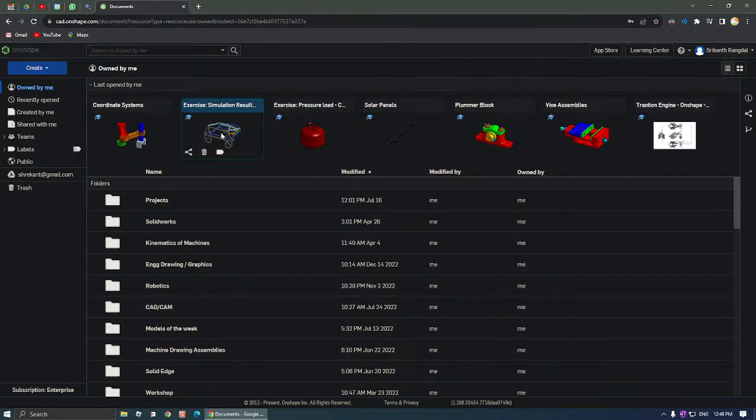But this software, Plasticity, uses the CAD infrastructure, the Parasolid, at its core, and so all the editing that we are aware of in CAD software, like moving a face or other edits, is available in Plasticity. And on top of that, we can just export a mesh of these 3D models that we generate to work in any of the 3D modeling and animation software.